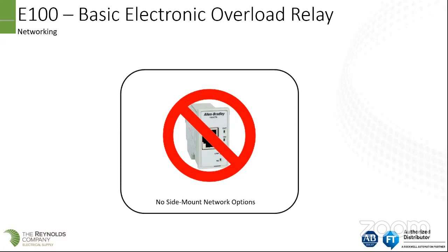If it's in a motor control center, work with the motor control center groups, most likely on getting a new bucket at this point, until there's a possibility to do an upgrade in the panel. That's one of the things that Rockwell has been looking at. We know there's not as much room in some of those, but just be aware of that. So if you do have them in MCC buckets, it's definitely something to start looking at if you have the Ethernet sidecar module in those, to get a plan forward to address that.